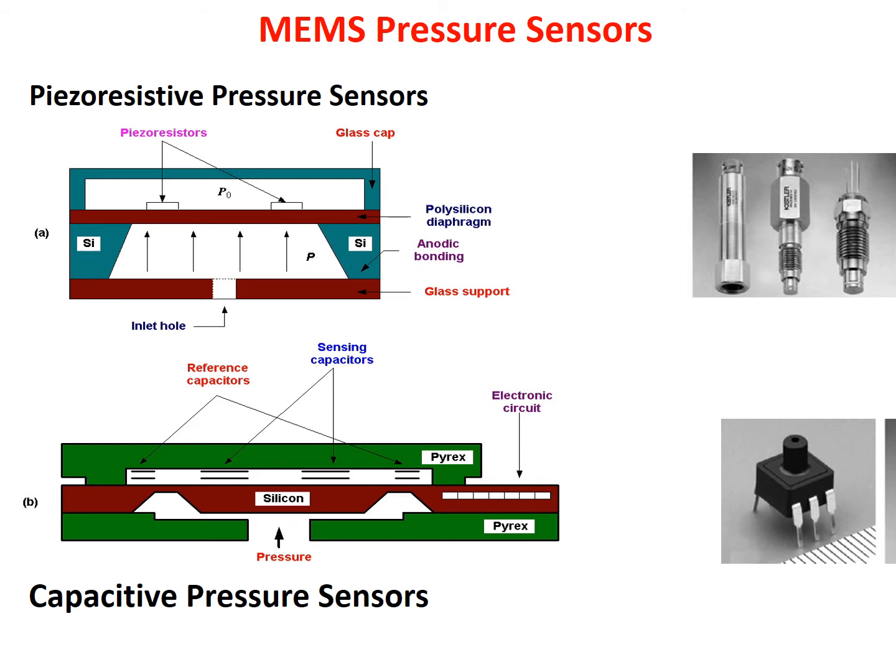So the basic point I want to highlight is that in the capacitive type, because of the applied pressure the diaphragm will be deflecting, and on the diaphragm we will coat or deposit some electrodes, and above that diaphragm we also have some frame where some fixed plates are there, and when the diaphragm is vibrating or deflecting, this gap will change, accordingly the capacitance will change, and this capacitance again we can connect to some bridge circuit which will give you the direct voltage output, right?